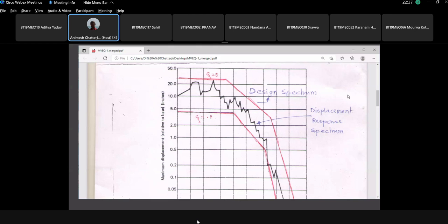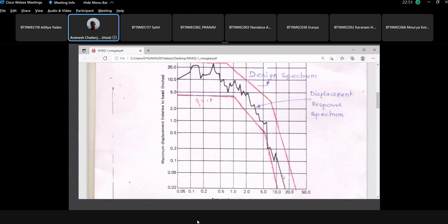Statue will have another value because the statue was not at all placed on the building. So if the natural frequency of the statue is somewhere here and the natural frequency of the building is somewhere here, which will fail? The building part. That is exactly what you will see today, an interesting thing.